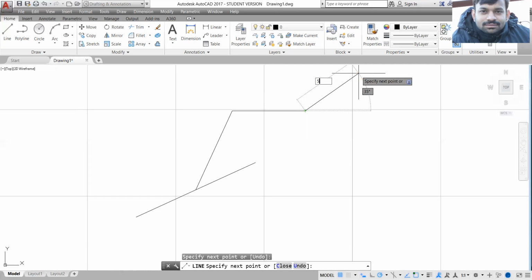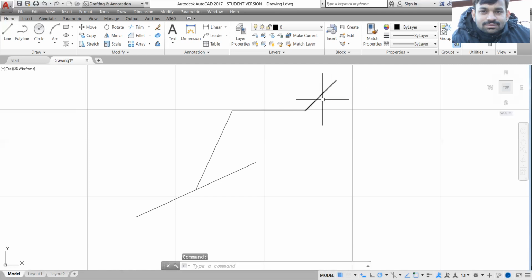from my keyboard. So as you can see, as I pressed tab, this lock sign appeared with the length rectangle and the 35° got highlighted. So now here I will enter 45 and press enter. So as you can see, a line of length 5 units is created and it is inclined at an angle of 45° from the positive x-axis. Okay, so this is how we can draw a line.